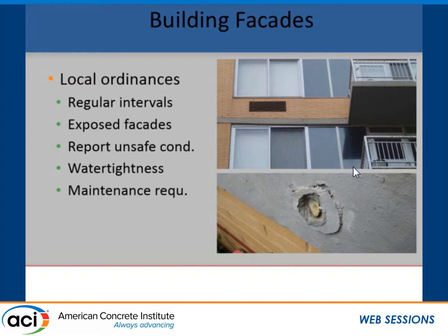There's also a requirement in the building inspection ASTM guideline for removal of unsafe conditions, and that's kind of the one that I question. I showed you that piece of concrete earlier. I'm not convinced that having an engineer remove unsafe conditions is the best idea, but it's an important thing to think about in terms of the completeness of the survey. You're expected as a design professional doing that facade survey to identify those conditions and help make them safe. So that's another couple of key pieces of our standard of care for evaluation of existing structures.